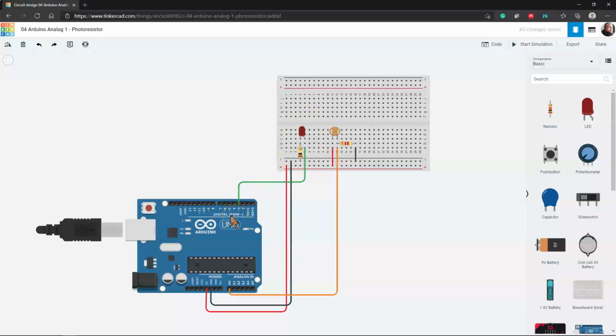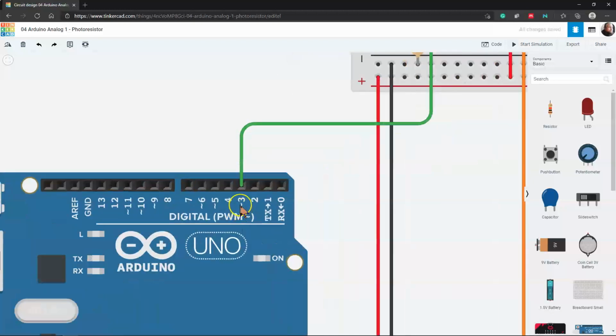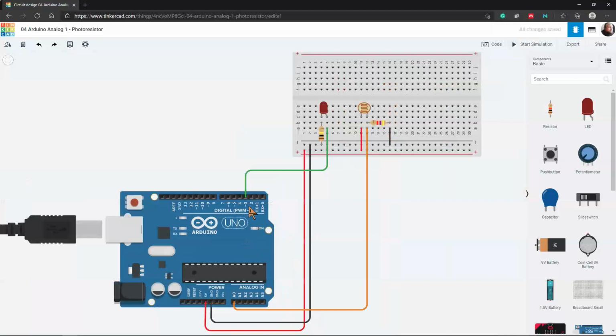Now, the key thing for right now is why I have it on pin 3: you can see that it is a PWM pin. So it'll allow us to simulate an analog signal going out and, in effect, fade the light. Because if we give it different levels of the actual current going to it, boom, it'll change the level of actual light that's going out.